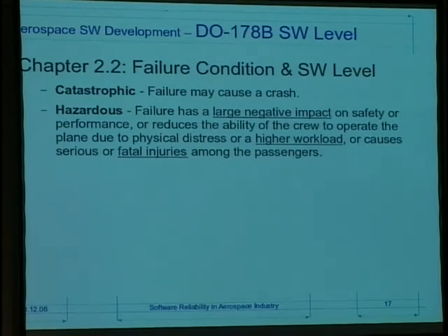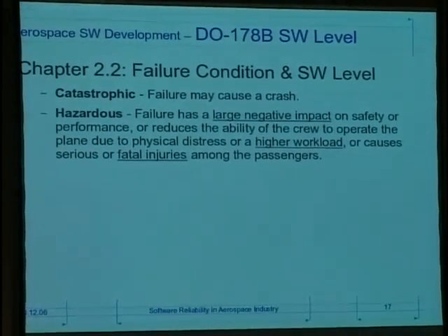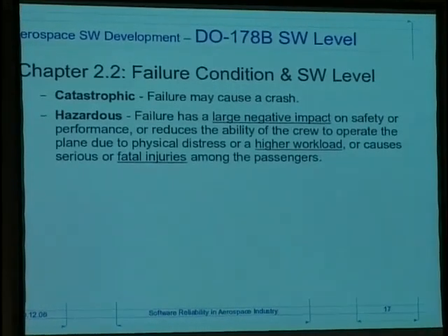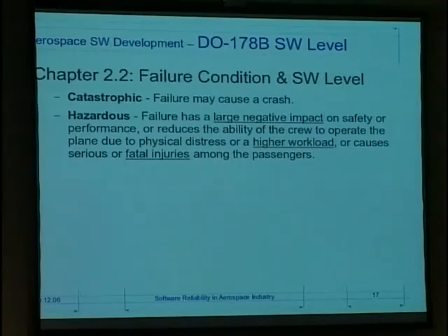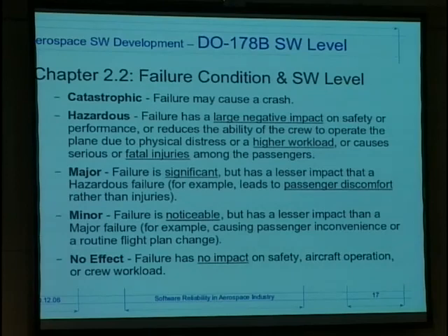The interesting thing is that the DO-178 and the developers have just recognized that a stressed crew and a heavy workload on a crew also endangers the safety of a plane, because if a pilot doesn't know where to look because of the many blinking lights, he will not see the mountain which is just in front of him. And then it goes to major, is it significant, to minor, where you notice it, but maybe the coffee machine is broken, or it has no effect at all. That's an interesting category because there are components which don't have any effect if they fail. That's very important because if they are identified as that, they either can be replaced or just removed from the system because you don't need it, or they are isolated from the system.